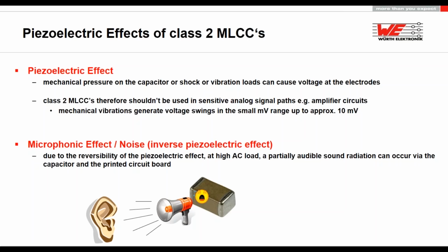It's not just the inductor that can make noise, it's also the MLCC, and this effect really shows at filters, at power modules and so on. You can really have strong noisy effects if you have frequencies or, let's say, not nice filter behaviors, and then you can get this strong radiation of noise.